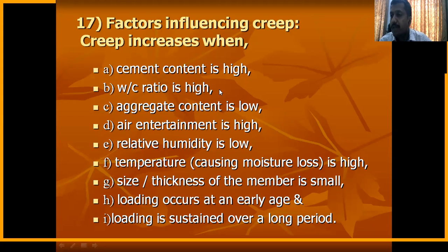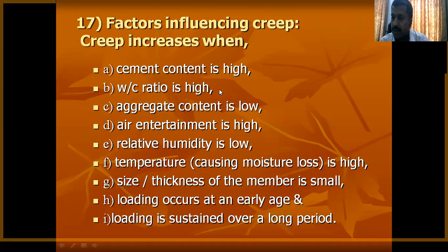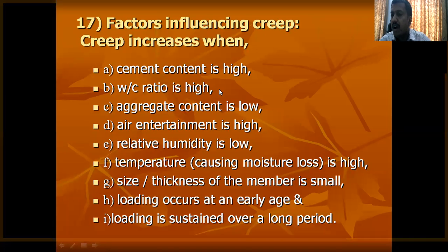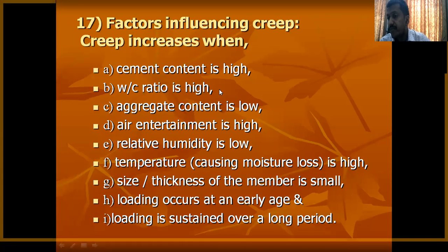So whatever coarse aggregate we are using, if you are using 20 mm coarse aggregate, the maximum water that we are going to use is 186 liters as per our IS. Okay, so how is this water to cement ratio going to form and how is it going to play its role? See,